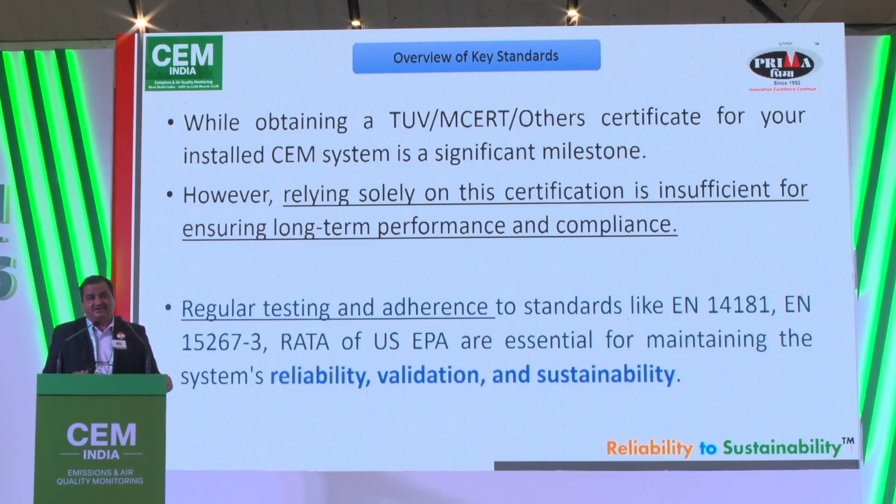When we went through the entire process of MCERTS certification under the EN 14181 standard, we understood that having a certified product is a pride for everyone, but the continuation of the reliability of the measurement data in the long term is always questionable. So regular testing and adherence to standards like EN 14181, EN 15267, and RATA of US EPA is essential for maintaining system reliability, validation, and sustainability.